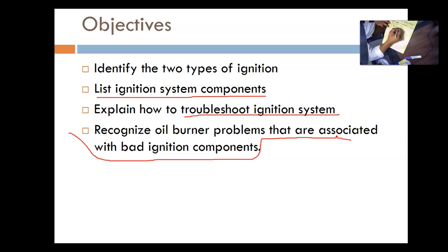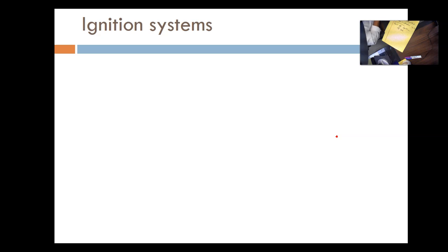15 seconds. It used to be 45, then 30, now it's 15 seconds because we do have the means to shut off the system in 15 seconds, and we are supposed to be able to recognize and see flame in 15 seconds. Some of the issues that will happen with delayed ignition as well, we'll try to address.